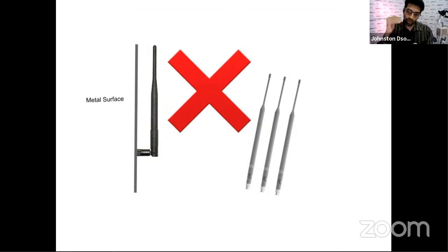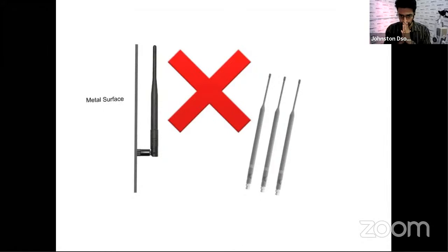So if at all you're putting your in-ear monitors or your wireless microphone receivers and transmitters in a rack, make sure that you get remote mountable antennas. Those are the helical antennas, the fish fin antennas. There are different kinds of antennas available, and you use them that way. If you're using a very professional high grade system at larger concerts or very high end applications, then it would make sense to get distributors, remote mountable antennas and very good RF cables.